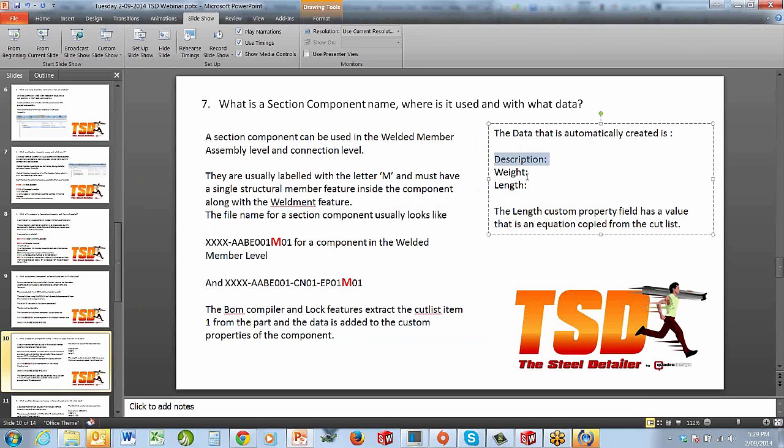Let me say that again. 500 parts on a rebuild is faster than 500 bodies in one part. If you want to prove it, try it. Anyway, SolidWorks' limitation is the CPU rebuilding features. So if you've got 500 features in a part, it's got to go through and rebuild all that. We can change a part fairly quickly with one body. Anyway, I'm not going to get carried away with that. We'll just continue on.